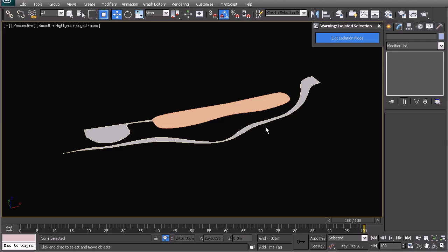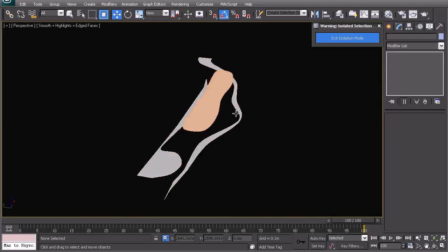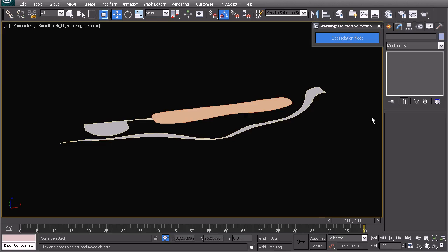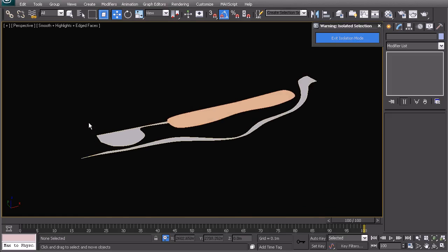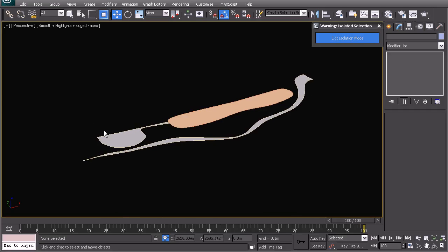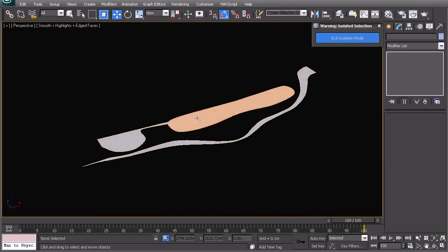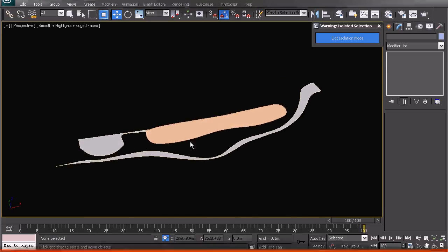So just to sum up for one last time before we go, what we've done in this video is we've edited the main mesh for the site just so that the current site fits into it neatly, and we've gone and identified the areas that we will use for planting. And it's important that the different areas that you have selected for planting do not overlap each other, one above the other. Otherwise, when you replicate your plants over it, you will have plants kind of being inside each other. You'll get the idea later once we get to the next video, just in a moment.